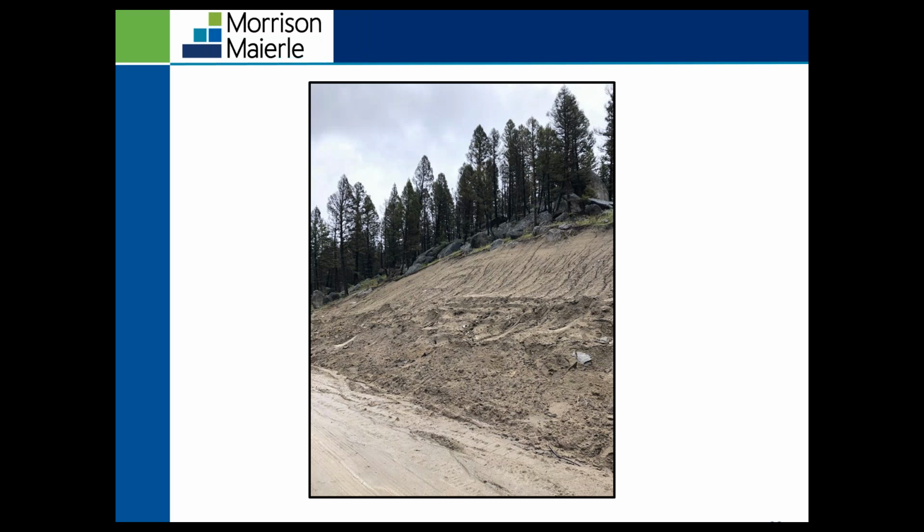This photo right here shows the disturbed slope that has no BMPs installed on the slope. You can start to see the erosion that's occurred, which has then removed a large volume of sediment from this photo. And actually, you can't see this, but it's discharging down. All the sediment crossed over the dirt road right there, went down another slope, and there's such a large volume of sediment that it overtopped the down gradient silt fence.